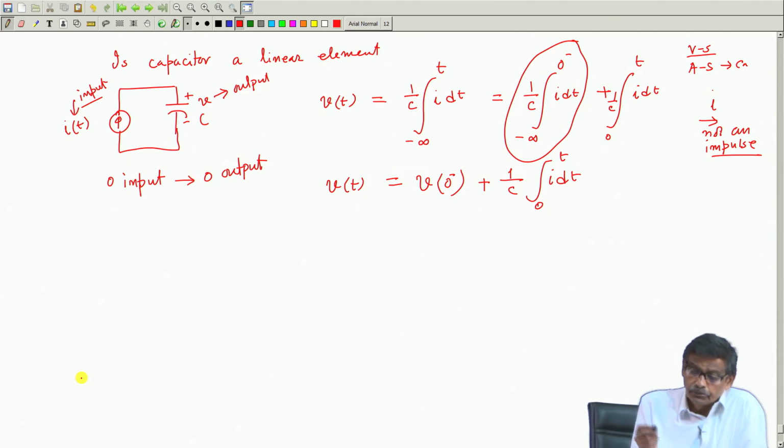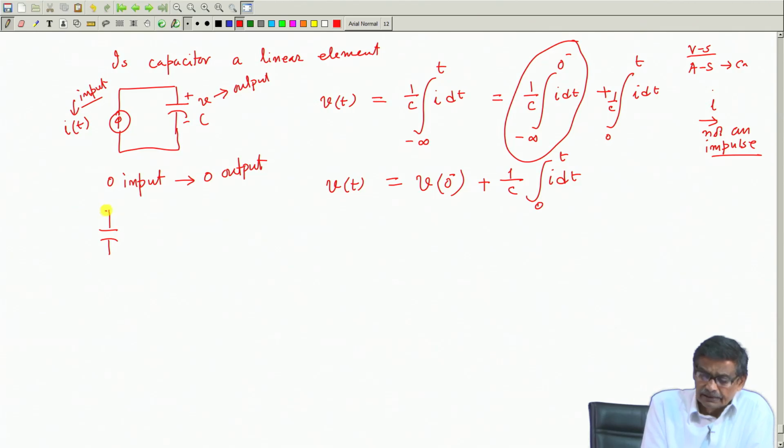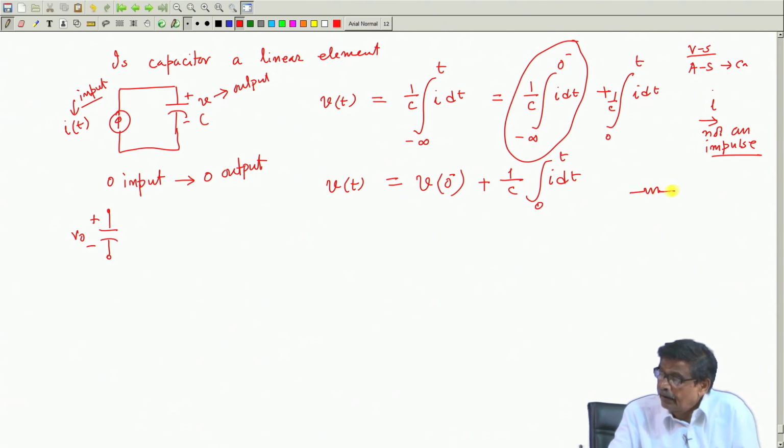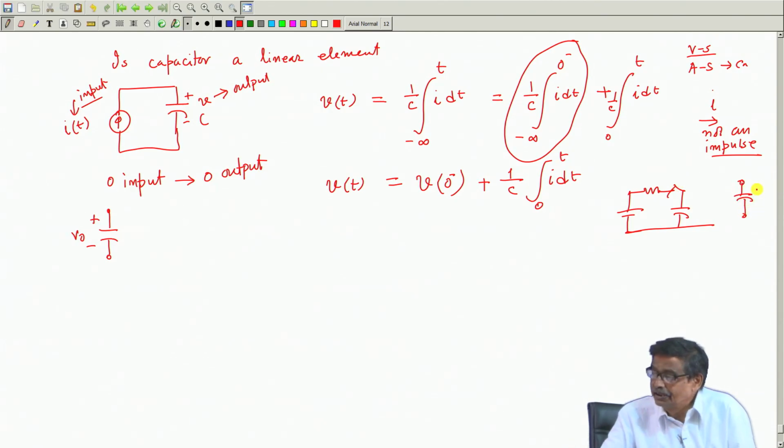Okay. But we know that a capacitor, if you charge it from some other circuit and leave it like this with some initial voltage V naught, what is the current now applied to the capacitor? 0, but it will be able to retain this voltage. It has been charged from some circuit and disconnected. For example, R, this capacitor like that, here is a voltage, you charge it, then after it is fully charged, open it. In ideal condition it will retain this voltage.